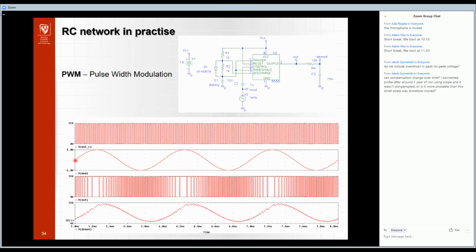So it is connected with the amplitude at the special moments. For example, these pulses I connected for this low amplitude, for amplitude equal to 0, and the wave is larger for higher amplitude of the modulating signal. So this signal contains information about the amplitude, about the voltage of the modulating signal.